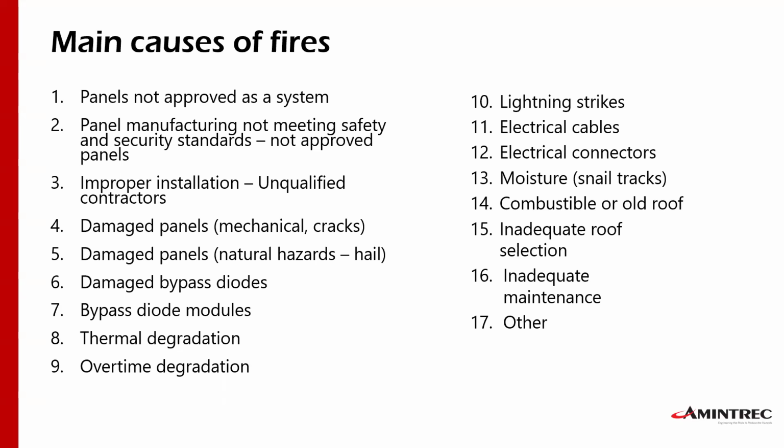Moisture, very, very critical. Moisture goes in with the thermal degradation and overtime degradation, because once you have degradation, eventually you will have moisture inside components, inside the panel, and you will have hot spots due to high resistance in connectors, or maybe on cables as well.